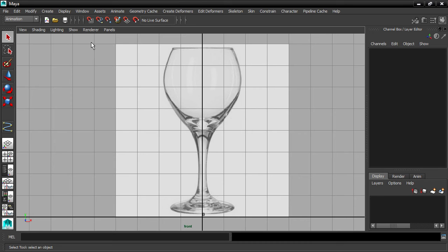The other thing that you need to know about NURBS curves is that they're very different from Bezier curves like you're used to from Illustrator and Photoshop. Bezier curves will freak out and have really strange results if you have 2 points in the same place. But NURBS curves really commonly expect you to have 2 points in the same place. That's how you define the sharpness of the curve. If you have 2 points right on top of each other, you'll have a sharper transition there. And if you have 3 points exactly on top of each other, you will have a hard corner. Okay? So again, that's very different to what you might be used to, but once you know those things, then actually NURBS curves are easier to use in Maya than Bezier curves, and they don't have as many issues.